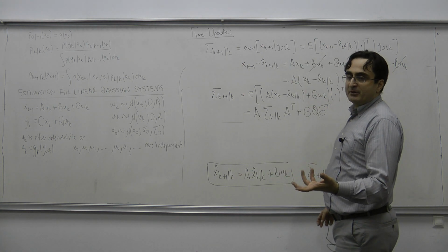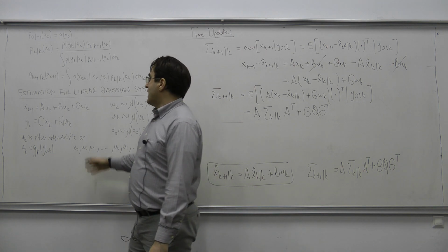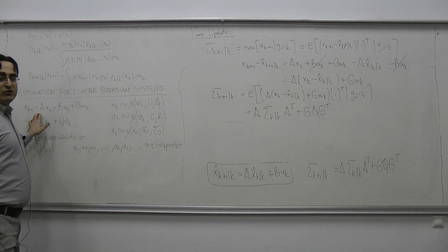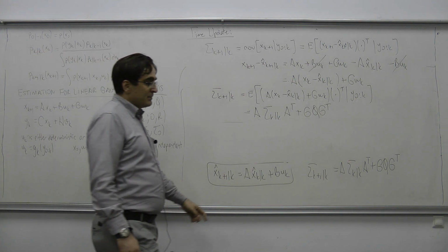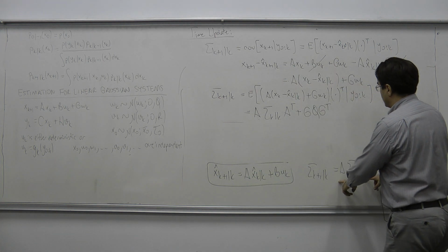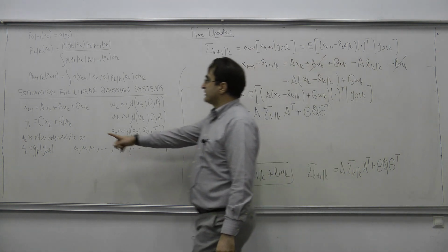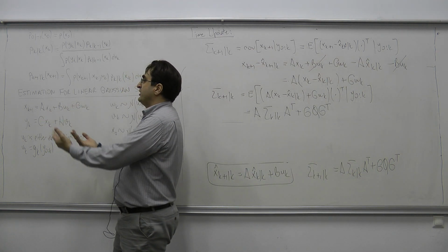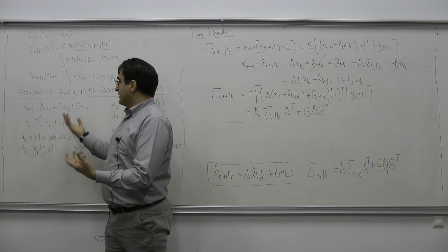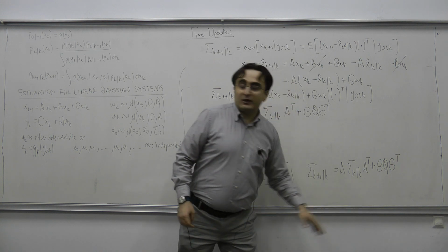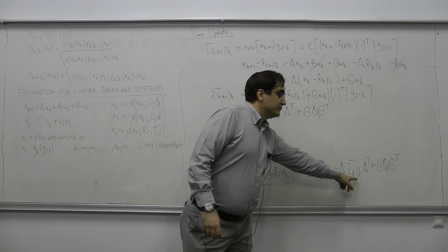So now what is happening in this covariance formula? Remember, the time update is about the propagation of the state in time, okay? And we know that that prediction cannot be exact because of the process noise, which is unknown. So this first term in the covariance update formula is the transformation of the uncertainty in the current state. We are trying to predict the uncertainty of xk plus 1 from xk.